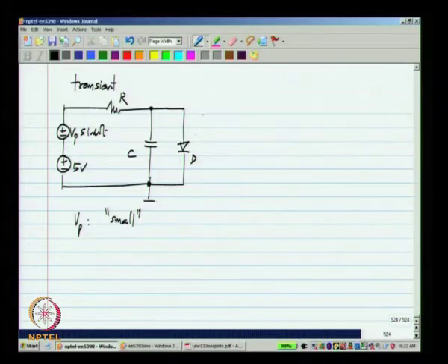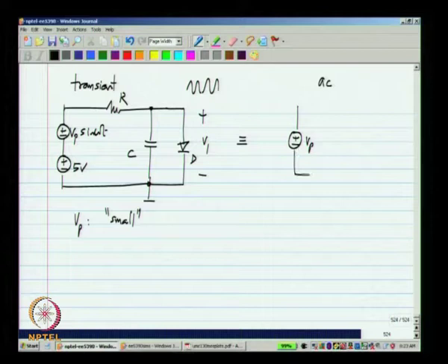In such a case, let us say you determine the voltage across V1 and it will also have a sinusoidal component, which will have a different amplitude from Vp, and it will also have a phase shift compared to the input sinusoid. Now, what you get from this analysis would be the same as what you get out of AC analysis for an increment of Vp at omega.